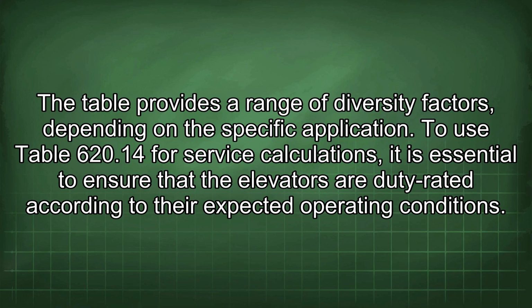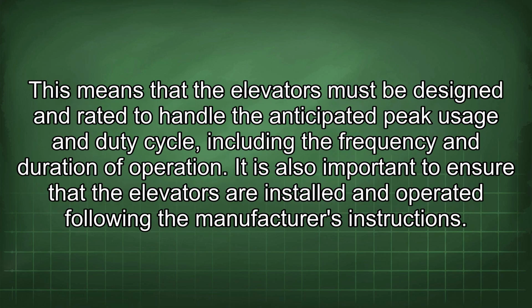To use Table 620.14 for service calculations, it is essential to ensure that the elevators are duty rated according to their expected operating conditions. This means that the elevators must be designed and rated to handle the anticipated peak usage and duty cycle, including the frequency and duration of operation. It is also important to ensure that the elevators are installed and operated following the manufacturer's instructions.